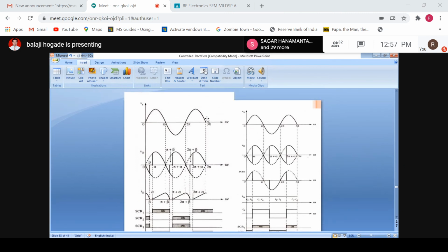So if in question on this single phase full wave fully controlled bridge configuration with RL load, if they mention, assume that the value of the inductor is very low as compared to the resistance, then you need to draw this discontinuous current conduction mode. They are going to ask this discontinuous mode directly or indirectly. They may ask the load inductance is low value, one and same thing.